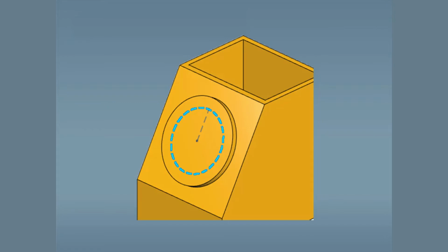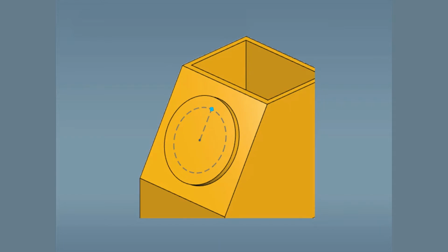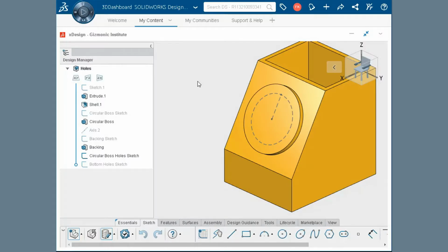We'll start with an existing sketch that represents the bolt circle and the locations of the center hole and the first hole, the source of the pattern. Note that the sketch is closed but visible. Generally, sketches will remain visible until they are used to create a feature, such as an extrusion. Then they will be hidden automatically. But even after they are automatically hidden, they can be shown and used to create other features.